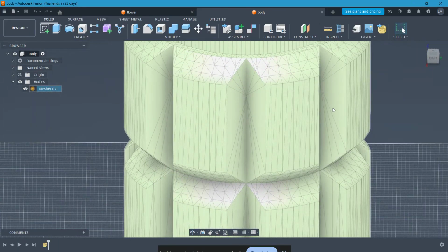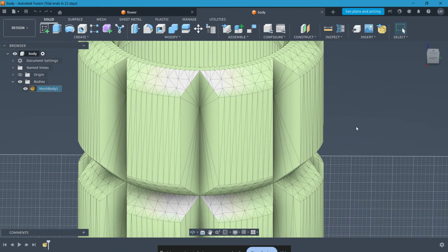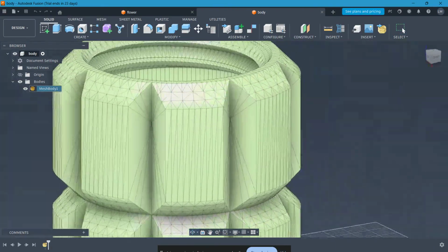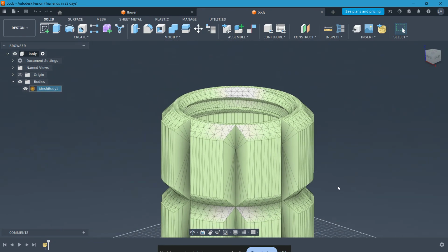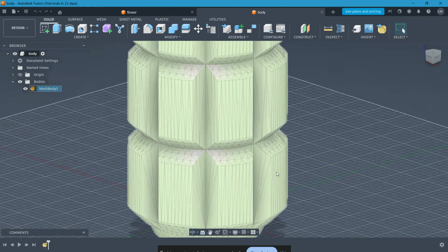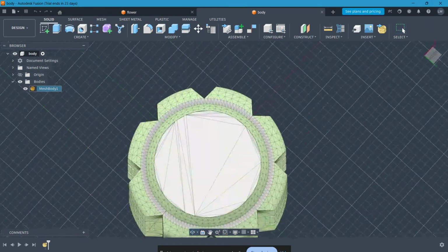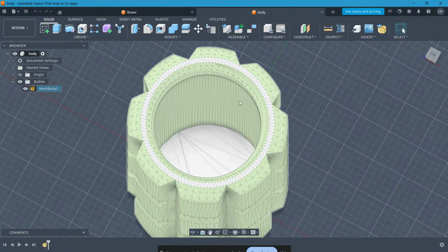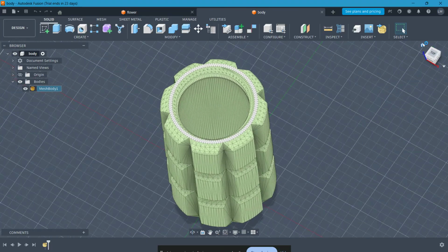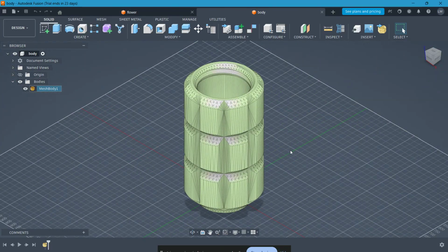Another common cause is very tight curves or offsets. When features become extremely small or curved too tightly, the geometry can collapse into itself during meshing. Shell operations can also cause this issue. If the wall thickness is too large compared to the shape, the inner walls created by the shell tool may intersect with each other. And finally, this error happens frequently with imported models like STL or STEP files. These files can contain hidden geometry problems that Fusion 360 struggles to convert into a clean mesh.